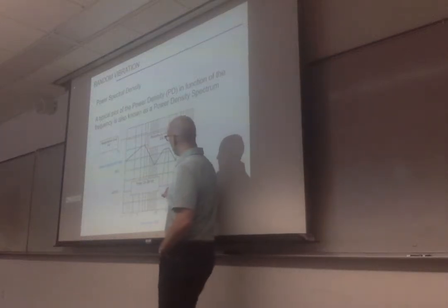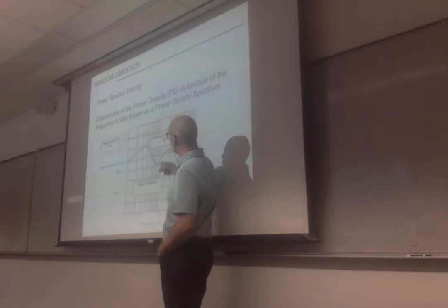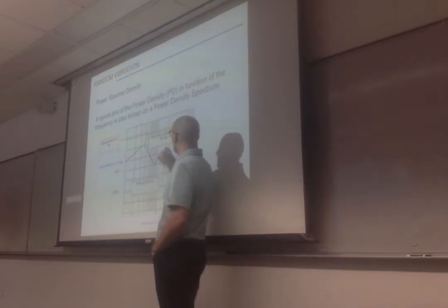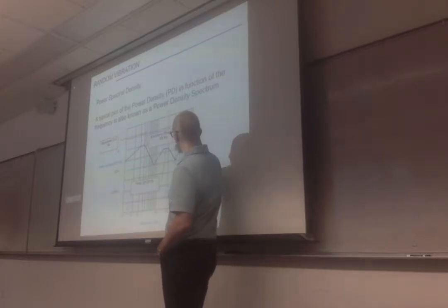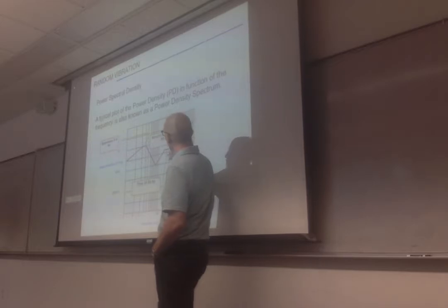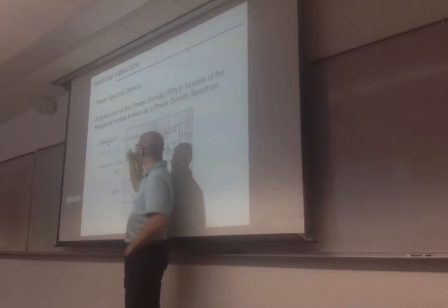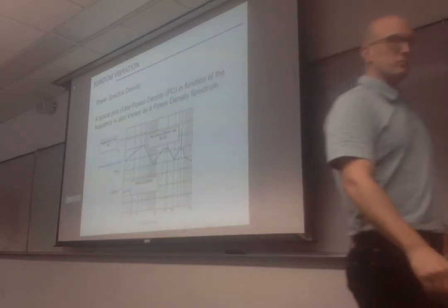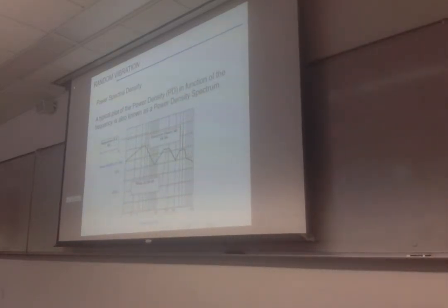So in here you see, we identify the peak vibration for road transportation around 15-20 hertz due to the tire, higher frequency here due to the structure, vibration of the floor, and the suspension is at low amplitudes, 3 to 4 hertz.